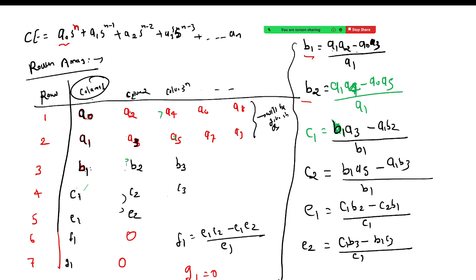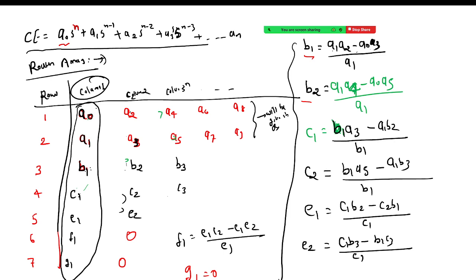The thing is that if this system has to be stable, if the characteristic equation is this, and we make this RH array, and if A naught, A1, B1, all these should be positive, then the system will be stable. That should be positive for a stable system.